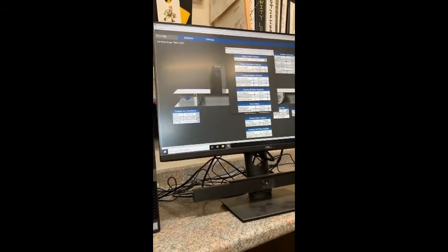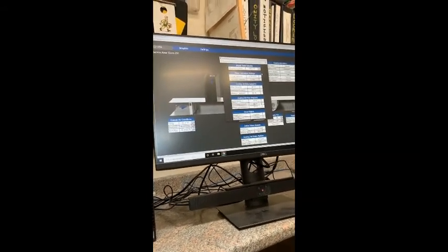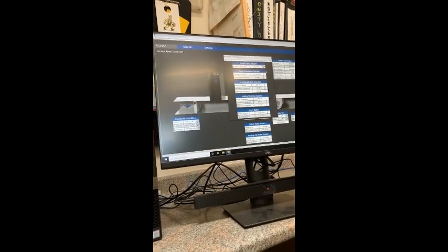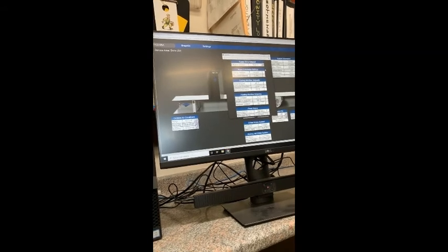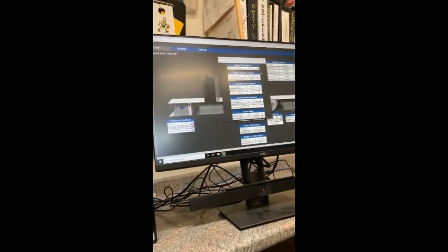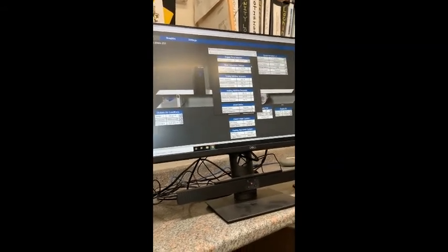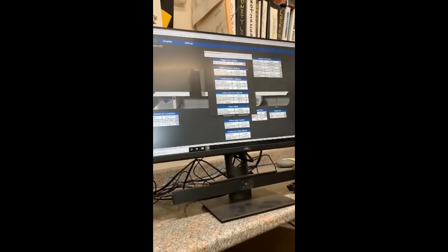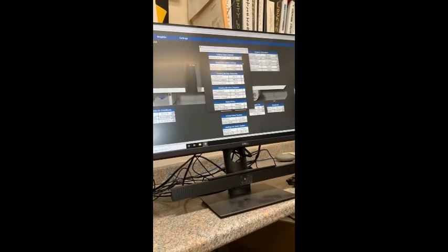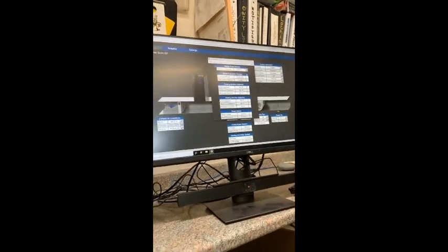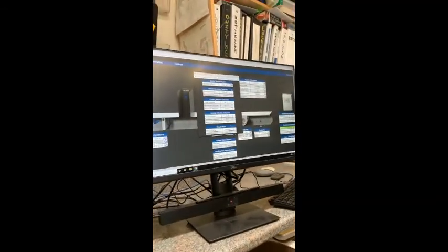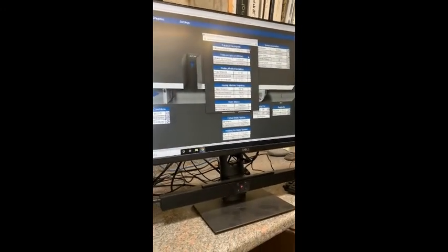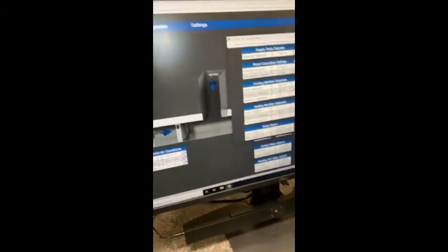So it resets based off of what mode it's in, heating or cooling, and the demand of it, and it will change a 1/10 of a degree every 2 minutes. The idea is to get these to run more efficiently with less complaints from the occupant, kind of like how a split unit runs. It doesn't just come on like an old Trane unit, compressor 100%, full cooling, then shut off, blows the 50-degree air for 10 minutes, shuts off.